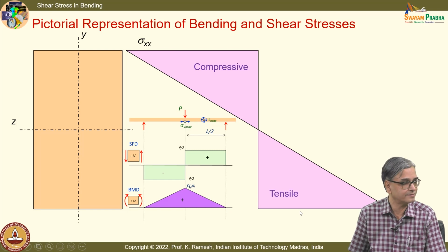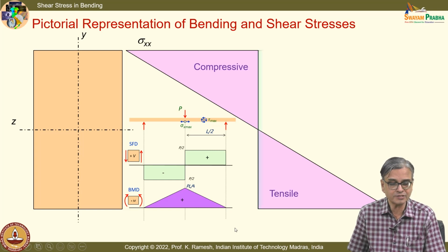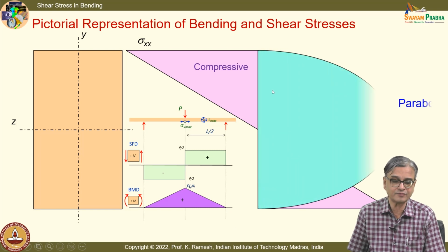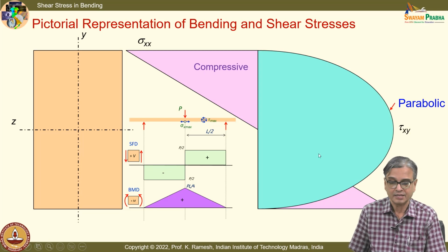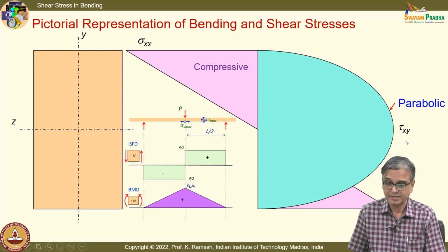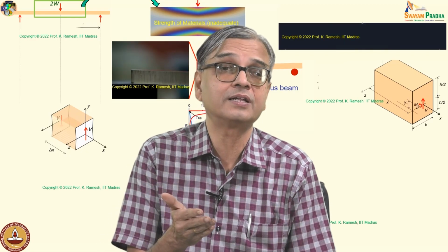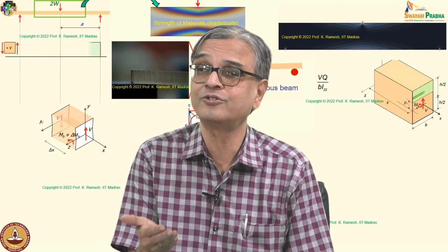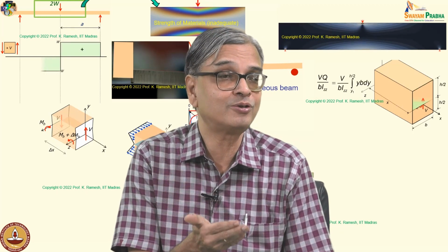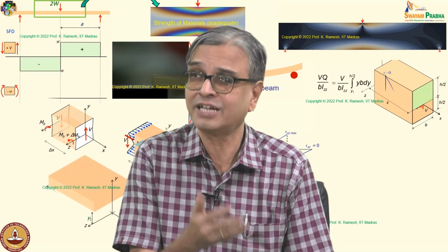Is the idea clear? And many books simply put the shear stress variation. The focus is only on showing that this is a parabola. And you get duped that shear stress magnitudes are comparable to tensile stress magnitudes. That is what you carry.